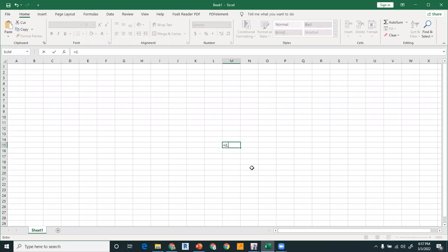So if you multiply 2.5 with 1.5, it will become 3.75, right? So this is the minimum, but we will take the pile diameter and multiply with 4. So it will be 10 feet, right?